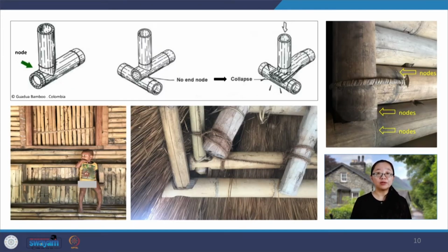The joinery is without nails. Almost all bamboo joinery are tied with rattan or coconut husk or jungle roots, and some joinery in the corner is made by cutting a hole in the bamboo, as can be seen in the pictures. In creating bamboo joinery, it is important to note that bamboo can crack. So in construction, using bamboo nodes is very important. Bamboo columns or beams need to have a node at both ends, or as close as possible towards the ends. If not, the pressure of a structure on the joint may crush the bamboo.